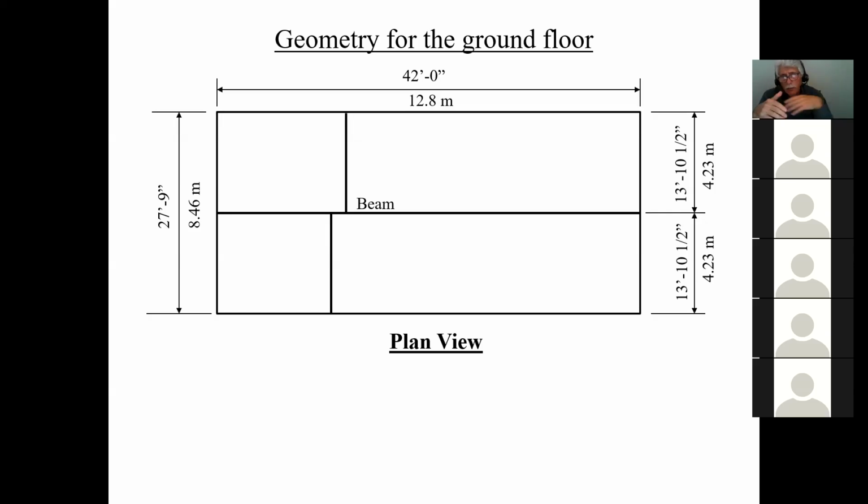Therefore, even if I'm carrying 16-foot joists on each side of the beam, I might be able to get away with a 5 ply, understand? And always stay within SPF number 1, number 2.